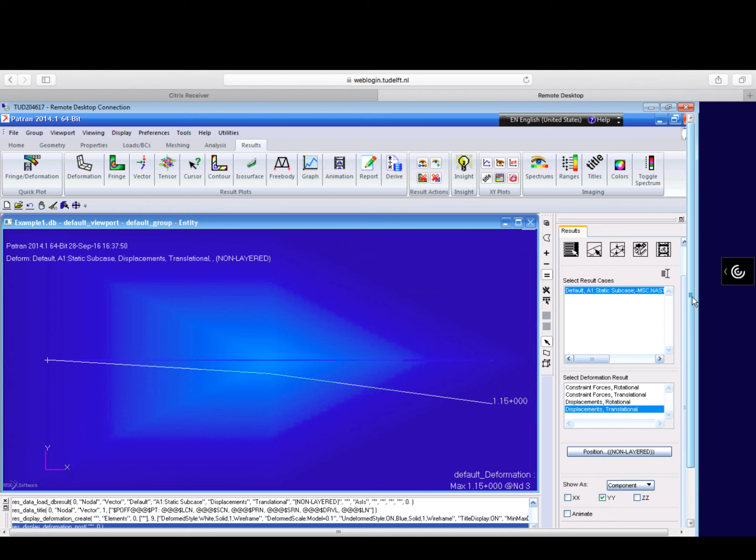So there are some differences, like you see in the kind of element that is used, but I would ask you to continue doing this analysis by changing the mesh a few more times to see if you get a much smoother transition, not a kink like this, and you will see a much smoother bend. So you can check for stresses also along the length, etc.